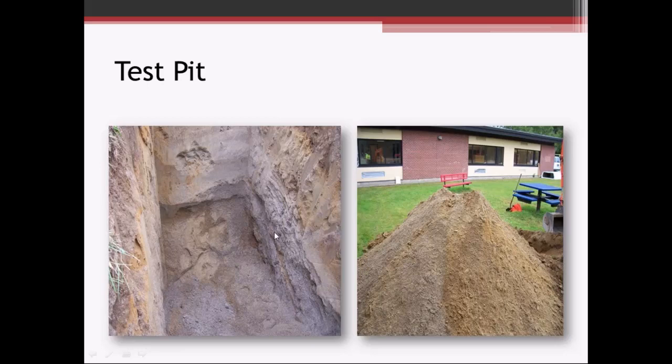However, the issue is backfill material or fill material for a site. This material is going to be excavated out, and it's going to have to be placed across the site. So it may make more sense in that case to take a representative sample from a stockpile where all those materials get mixed together.